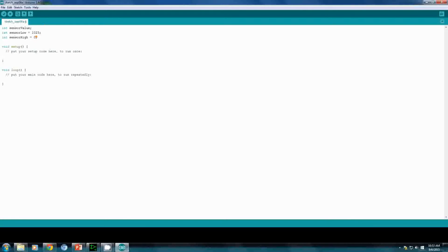not these numbers the other way around? We initially had to calibrate this photoresistor. Just the makeup of these components, they all don't read exactly up at 1023 and down to 0.